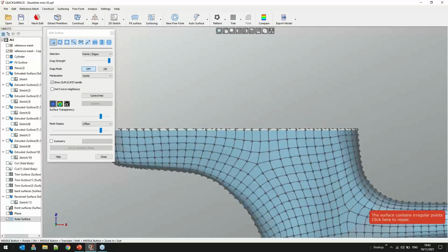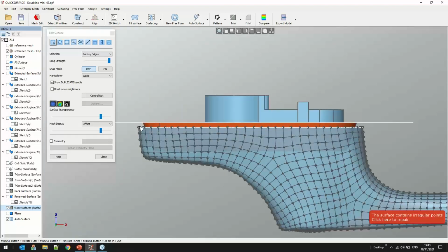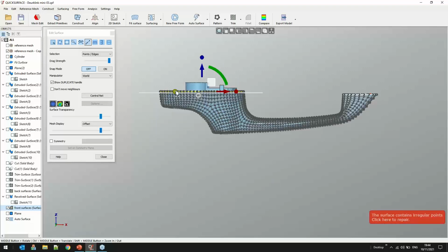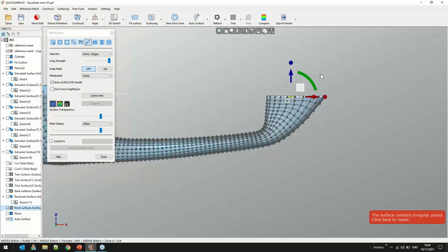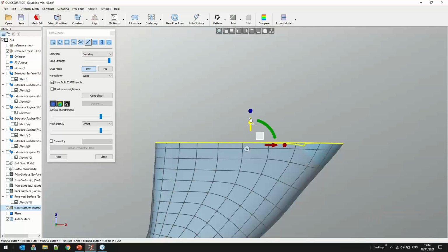So what I need to do now, as you can see, this is my shape. I can just double click and we'll use our interpolation tool. We'll just move this up so it goes more than it's needed. This is what I did. I'll double click. I will just need to select the boundaries to take the whole boundary, and we'll extrapolate.